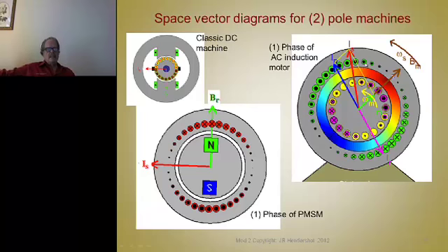And in the case of a two-pole motor at 60 hertz, the RPM of that stator field would be 3,600 RPM. 4-pole would be 1,800 RPM. 8-pole would be 900 RPM. A mathematical relationship. But the actual rotor doesn't go that fast. It goes slower than that. It has to go slower than that.